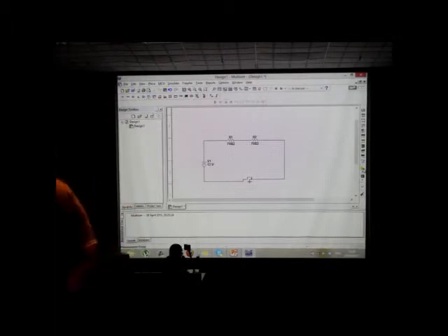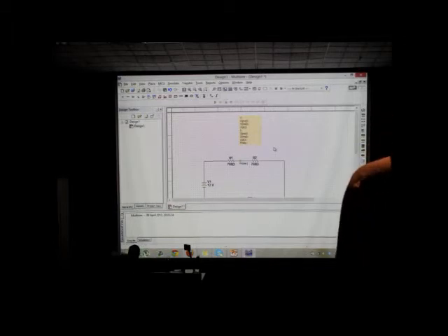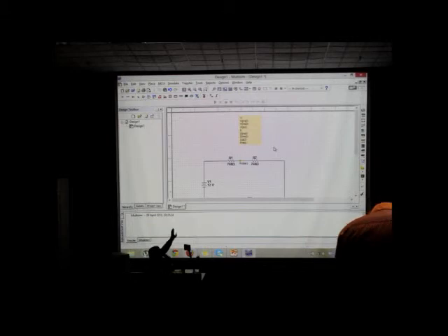So what you have to do is get this measurement probe and put it here. You just click here, and you have the probe. This is probe 1. This thing will give you the voltage and everything here, with RMS voltage, peak to peak, and DC. You can get everything. In PSpice, you only get the voltage and only the current. Here you get everything actually, whatever is happening.